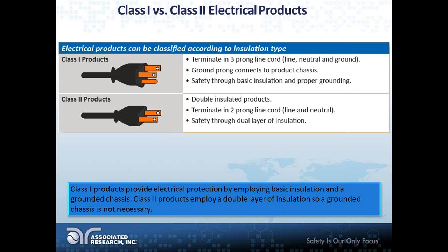So instead of just basic insulation, you also have double or reinforced insulation to make sure that should even one layer fail, you still have that second layer to protect the user. Again, a second level of protection. So this is something to keep in mind.